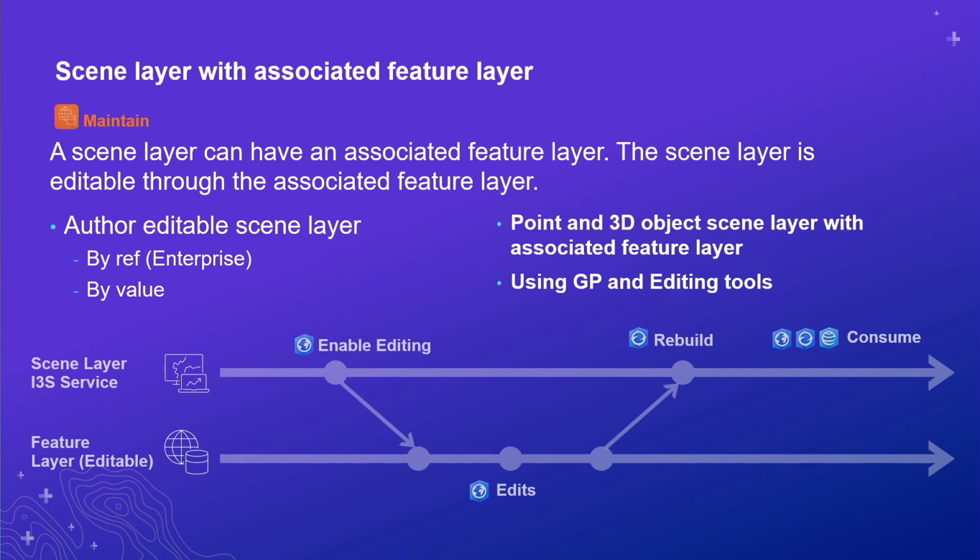Now users with editing rights can edit the scene layer in ArcGIS Pro. For us, it was very important that all the editing workflows you already have for editing feature layers remain the same for editing scene layers. As a user, you don't see any difference if you edit a scene layer or a feature layer. The only difference is that users that consume the scene layer without editing rights will not be able to see your changes until you have recreated the scene layer cache as a full or partial update.